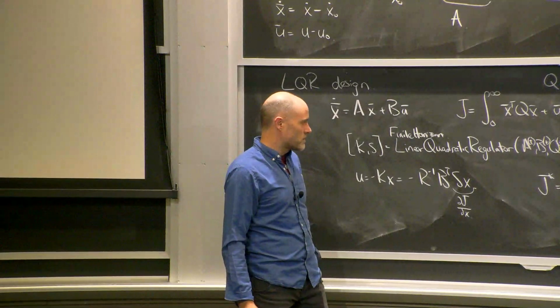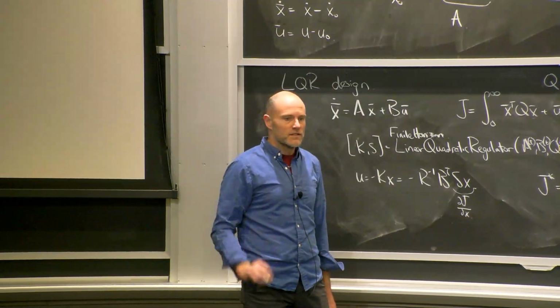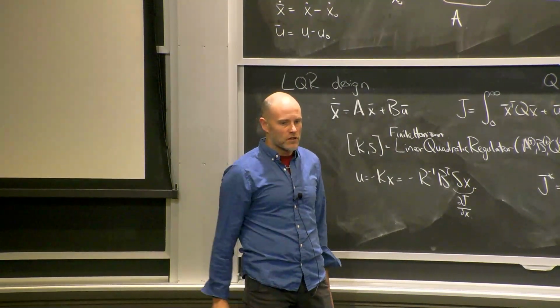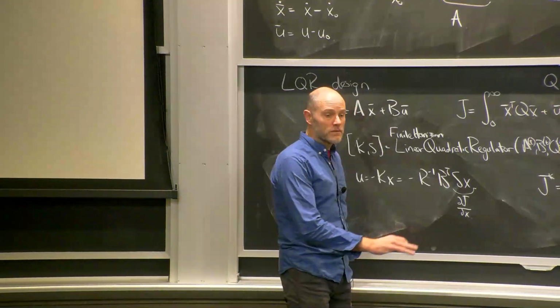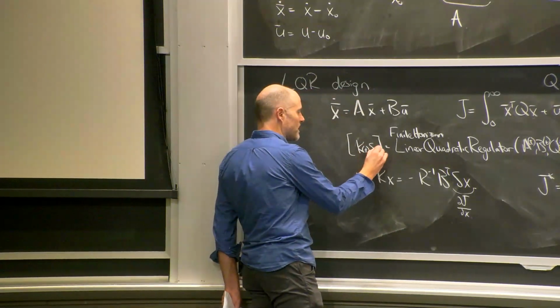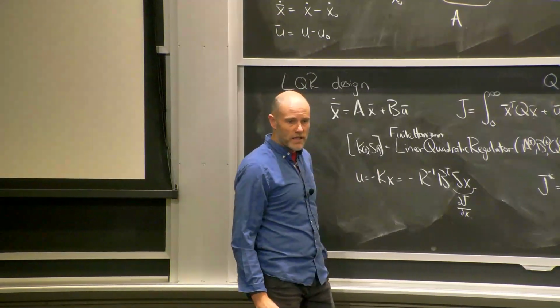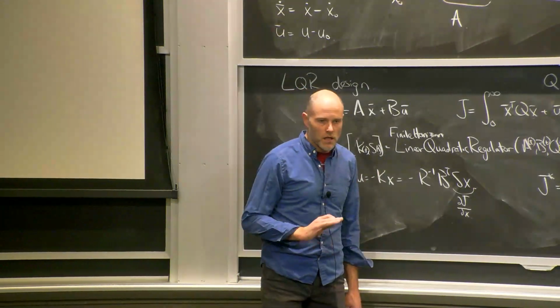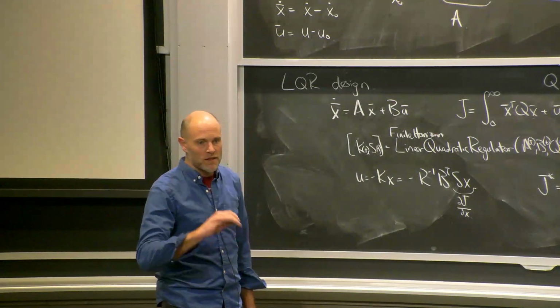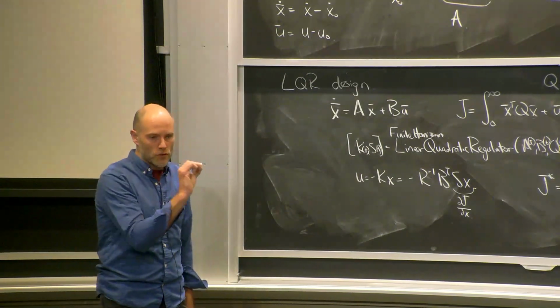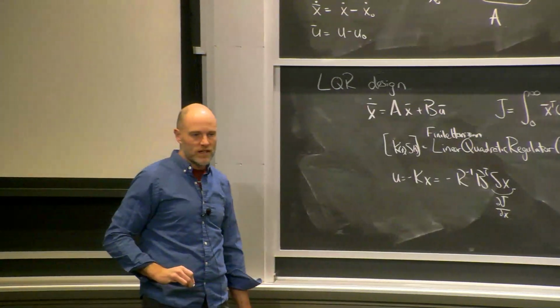And you can hand in a final cost, a final horizon, final time cost. It's going to be very similar, and you'll get back a K of t and an S of t. But a lot of the machinery will extend, and that's what we get in our moving coordinate systems, if we're linearizing around a trajectory instead of around a point. We get to this kind of a formulation.